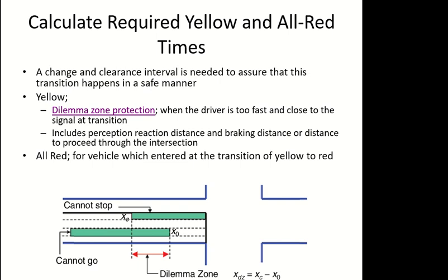So this is the time when we have all red. Your signal is red and the next one is waiting on red for a few extra seconds. So all the signals are red. This is called all red or clearance interval.